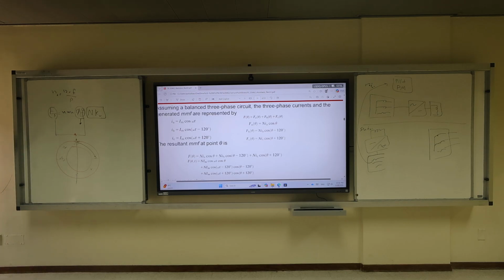Having said that, for big synchronous generators, a small movement of the rotor will generate a full sinusoidal cycle. Get it? Because they have 20 poles or 30 poles, a small mechanical rotation would guarantee you a full sinusoidal electrical output.